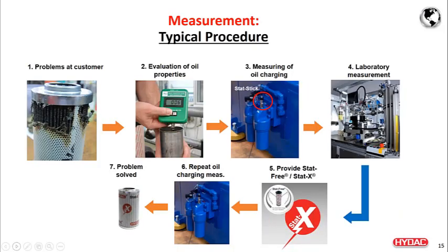So typically, this is how HYDAC processes this type of inquiry. When customers mention electrostatic charge and discharging, the first thing we talk about is the conductivity of the oil. We currently have a few conductivity meters out in the field with filter application engineers in different regions, and of course in the lab in Bethlehem. You can either have the filter application engineer in your region help you discuss the conductivity of the oil, or you can send about 200 milliliters of oil to HYDAC to test the conductivity.